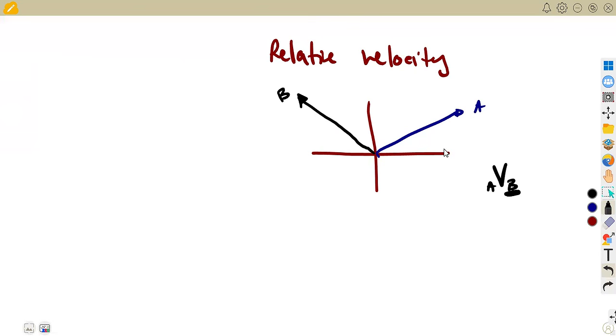I talked about how you're going to take this depending on the angles that you're given, the angle here, and also the angle that is taken up to this point, or you can even use this angle as long as you understand how to use your velocities in addition. But if you take all your angles from the positive horizontal axis going in the anti-clockwise direction like this, you add, meaning A is going to be added to B. There's no subtraction, you add. That is an easier part because you follow one thing. You just have to know what is the difference. So that was for a relative velocity.